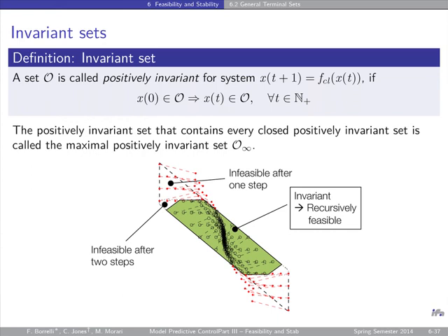So what do you need to define an invariant set? Summary: invariant sets are defined for systems without inputs. And you need to define the initial set, calligraphic X. So I have a system, I have constraints. Tell me the set of states for which, if I start in there, I will always be in there. And there are MATLAB tools that will accept a linear system, will accept a box, and will give you as output the green set.